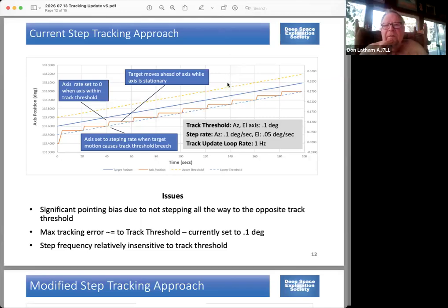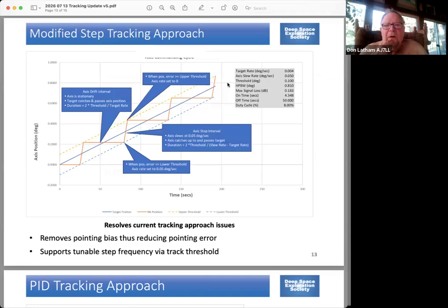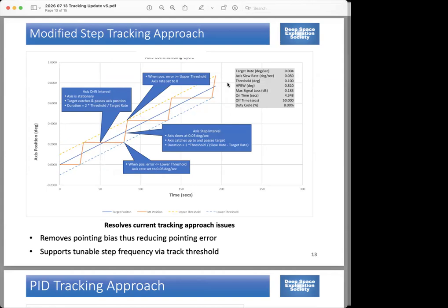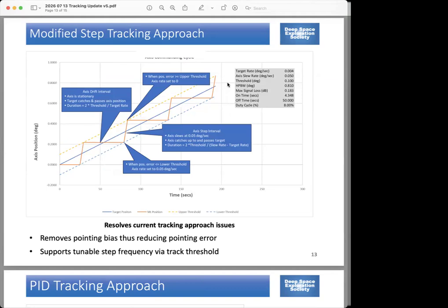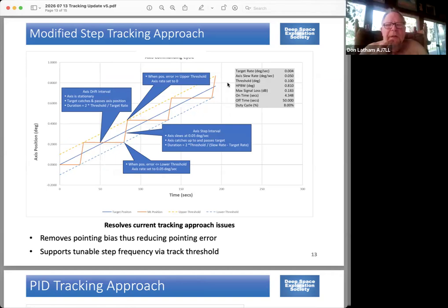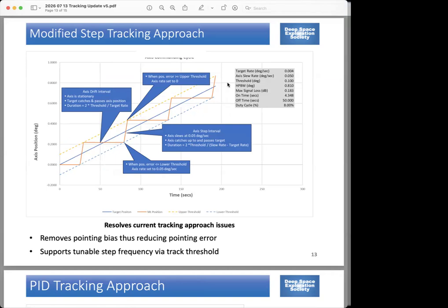I have one quick one, Glenn. What's the Modbus rate that you're using? The Modbus itself is internal to the encoders. We're basically querying the encoders across TCP/IP. I think I'm doing it 100 times a second. So we're reporting it 10 times a second and using it about once a second. But with the new approach, it won't be like that anymore.